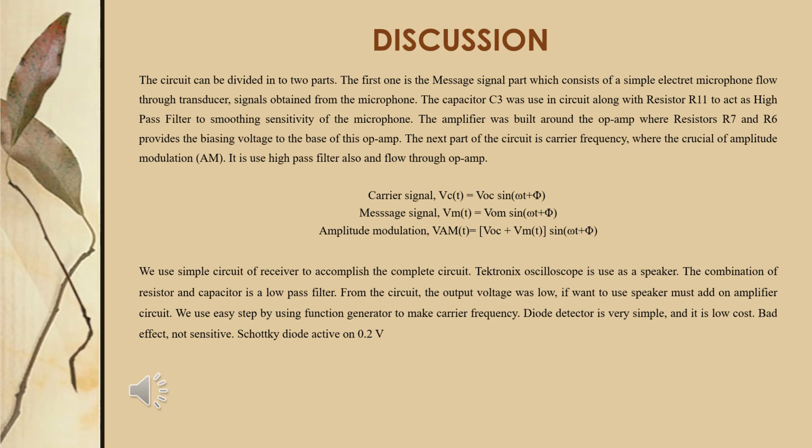For the receiver part, the receiver will receive the AM wave and demodulate it by using the envelope detector. Similarly, the frequency modulated wave is demodulated using the frequency discrimination method. The tuner circuit and the mixer circuit should be very effective, while the receiver takes the amplitude modulated wave as an input and produces the original audio signal as an output. Selectivity is the ability of selecting a particular signal while rejecting the others.